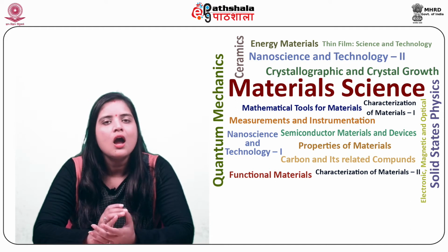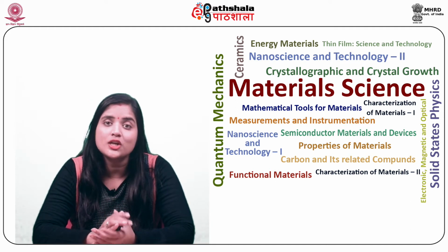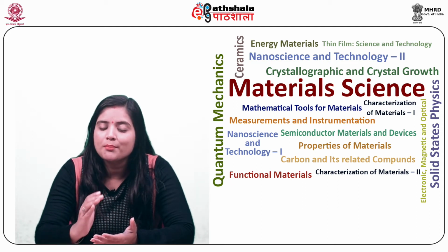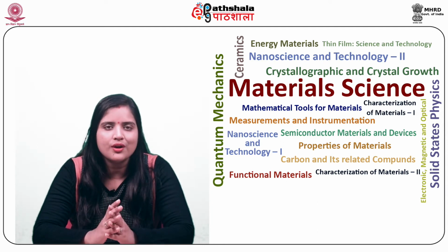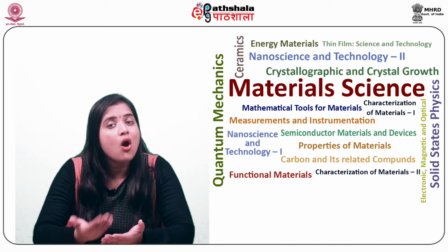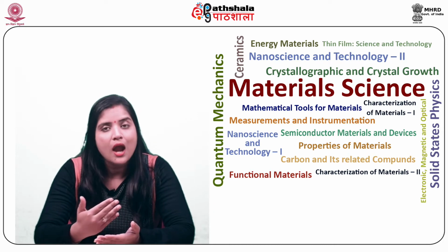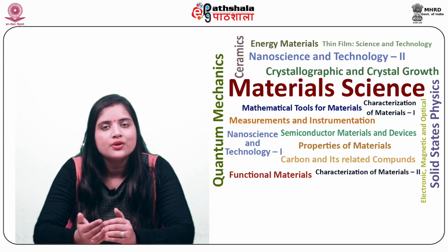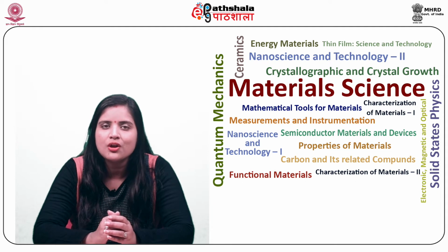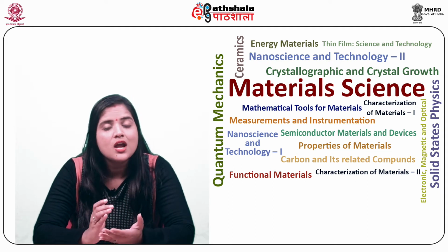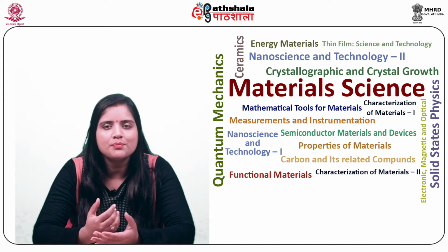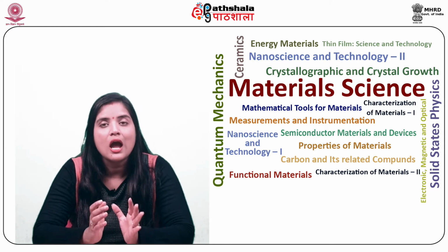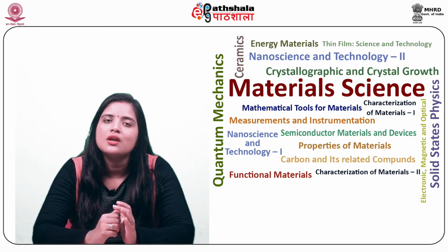The fundamental principle underlying the capacitance voltage measurement involves applying a variable voltage to a metal insulator semiconductor, also known as MIS, or to a Schottky junction, and then measuring the junction capacitance. In order to derive the relative information of the DUT, that is, device under test, physical properties, the correlation between the measured capacitance and the applied voltage is utilized.